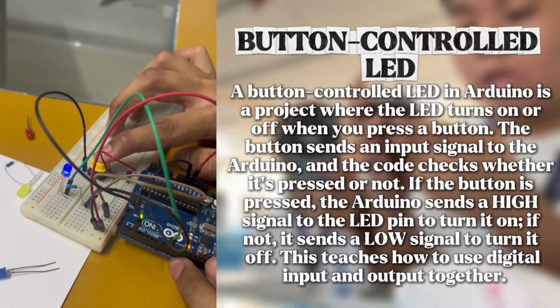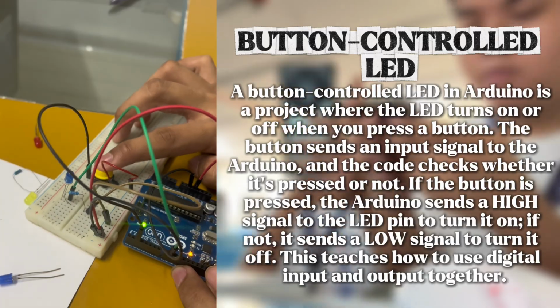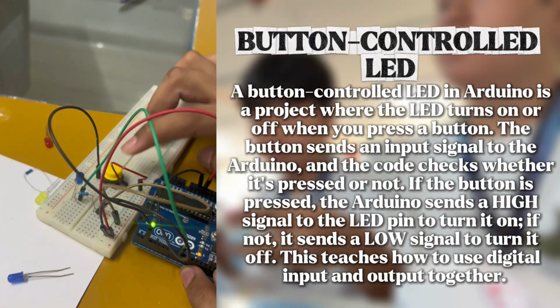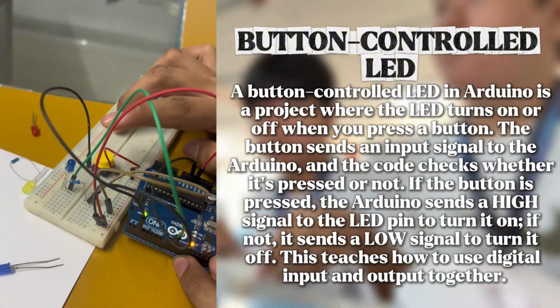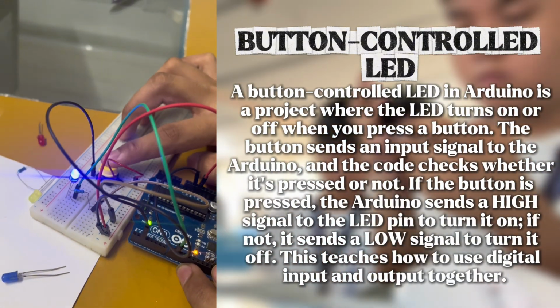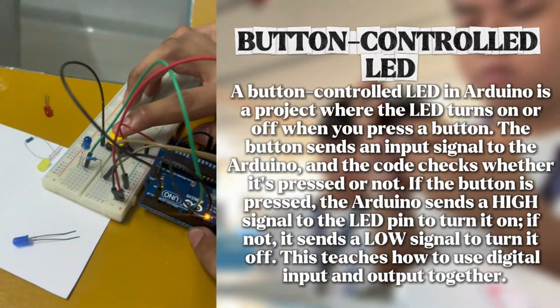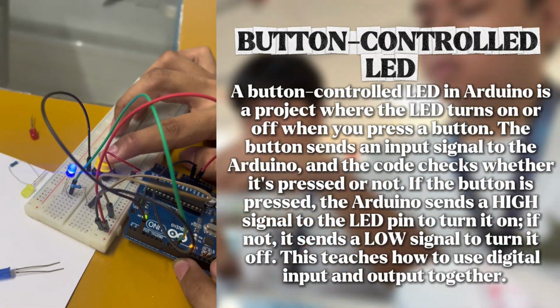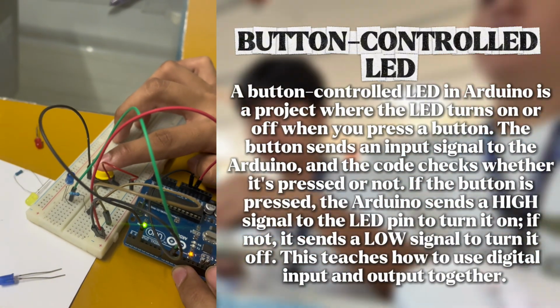A button-controlled LED in Arduino is a project where the LED turns on or off when you press a button. The button sends an input signal to the Arduino and the code checks whether it's pressed or not. If the button is pressed, the Arduino sends a high signal to the LED pin to turn it on. If not, it sends a low signal to turn it off. This teaches us how to use digital input and output together.